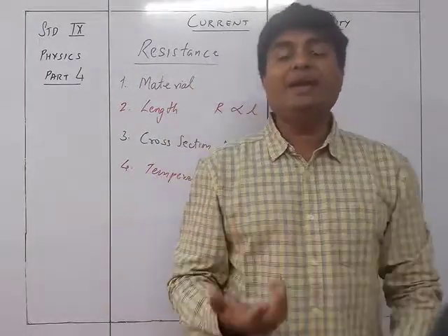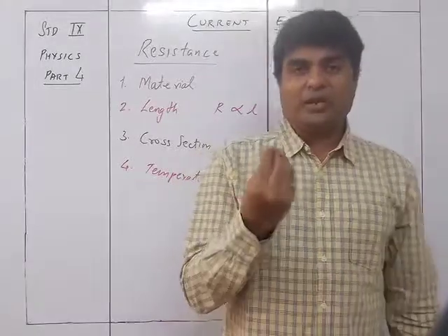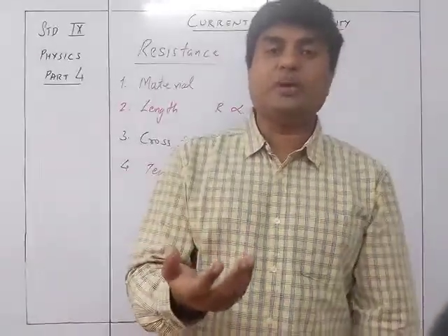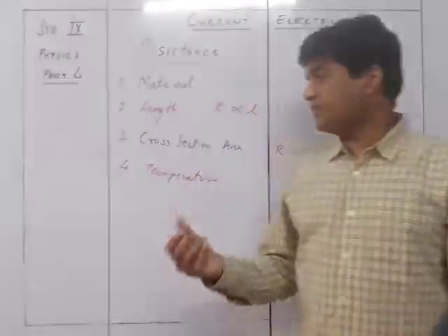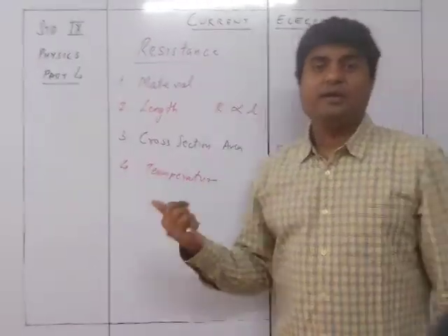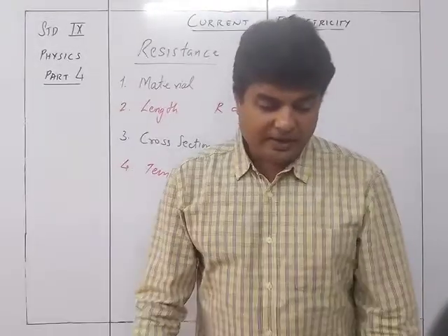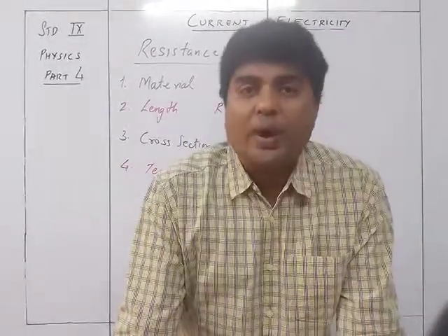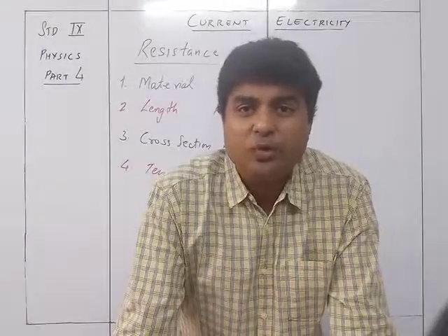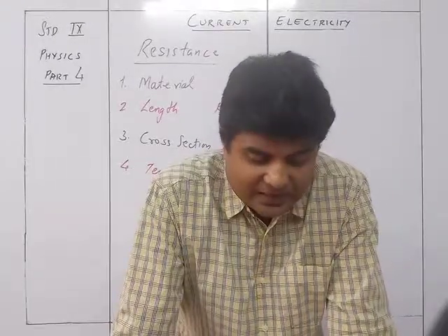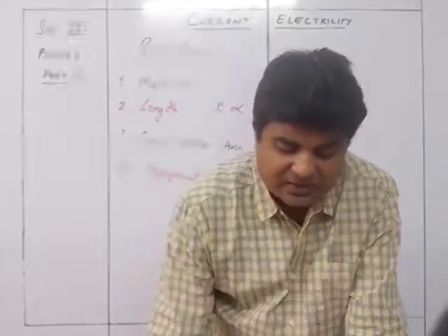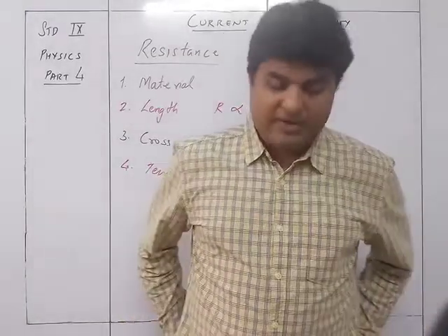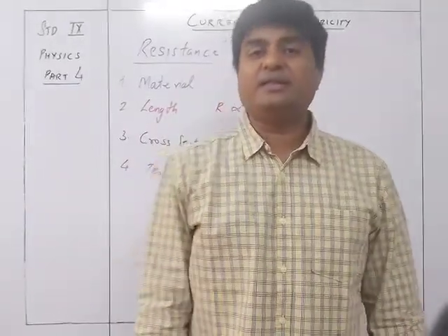So the internal molecular structure is going to have more kinetic energy, so more motion, and that's why the chances of collision in case of electrons with a higher temperature is going to increase. So that's why if the temperature of wire increases, ions in it vibrate more violently. Ions inside are going to vibrate more violently. As a result, the number of collisions increases, and hence the resistance of the wire increases. That means the resistance of the wire increases with the increase in the temperature.